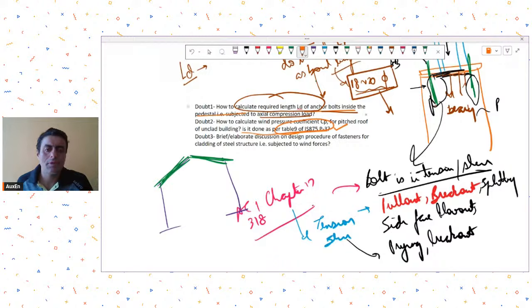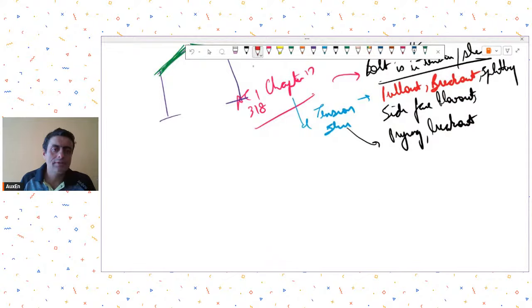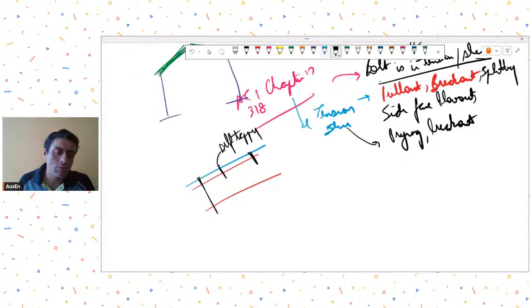Yeah, I do agree. Then his next question is a brief or elaborate discussion on design procedures of fasteners. See, fasteners means where you are connecting your sheeting to purlin. If this was a sheet, basically you will put fastener screws. Now those screws can be self-tapping, or in some conditions you put a J bolt. You may put a J bolt like this.